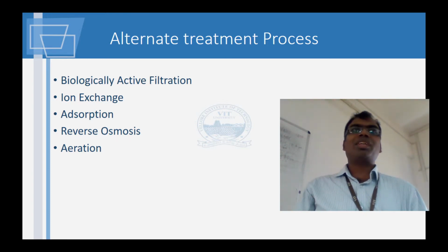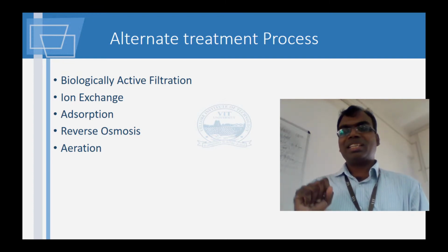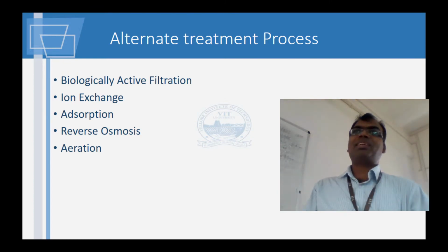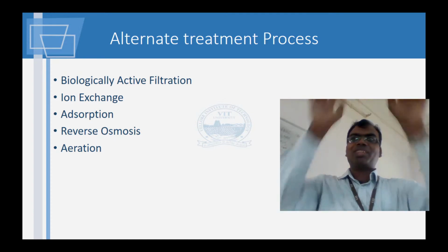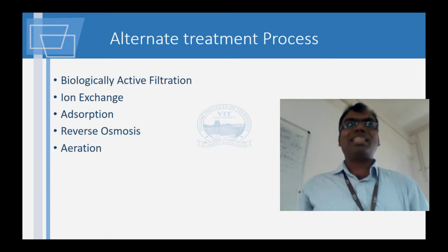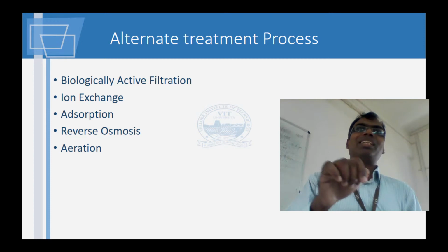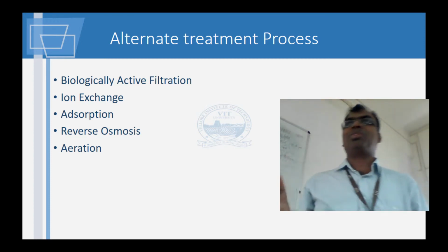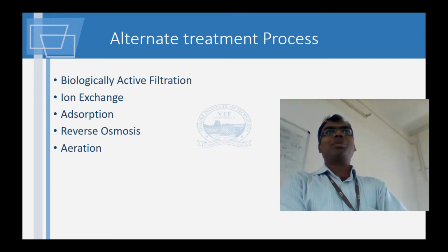The old Aquaguard, the original Aquaguard, I have split it to the last bit and I reassembled it. It's very good and it is so simple that it cannot fail. There's one UV lamp chamber, the other is the activated carbon column. So you'll see the old Aquaguard, there are two columns and one middle center box. That is the electronics that controls only the UV light. So it has one light sensor. If there's turbidity in the water, it will stop the flow. It senses only turbidity.